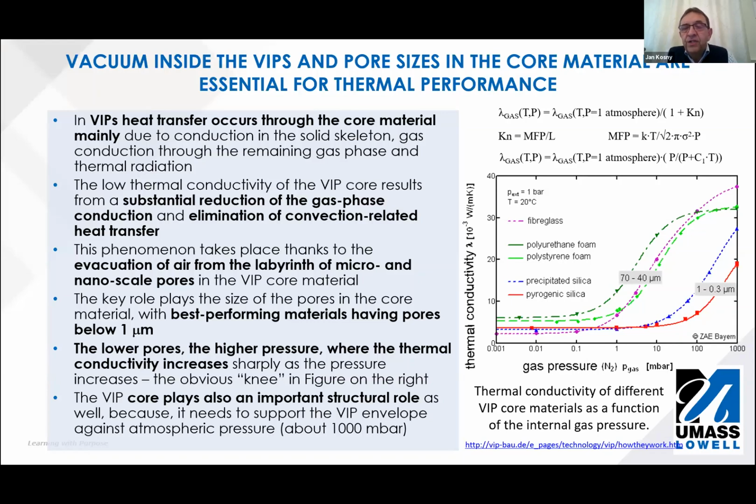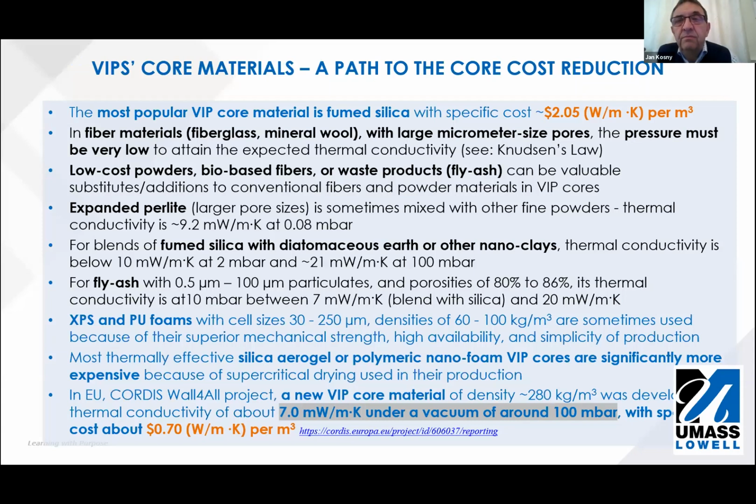Materials of higher size of the pores require much higher level of vacuum to reach that good thermal conductivity. And you can see that materials of higher pore sizes increase their thermal conductivity at a vacuum level in the neighborhood of 1/10 of a millibar, while aerogels can do this still up to 100 millibars. This is the major message about thermal conductivity of the pores as a function of vacuum level.